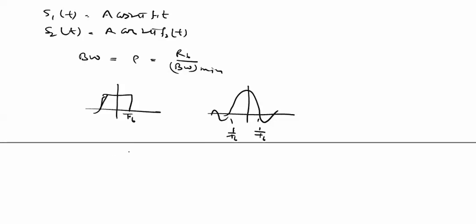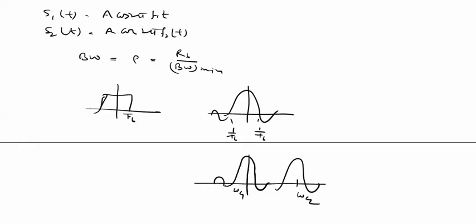If we transmit two different frequencies, means two different components aligned at particular carrier frequencies, omega C1 and omega C2. The difference between these two is omega C2 minus omega C1, plus this component 1 by TB and this component 1 by TB. Both are added for bandwidth purposes, means 2 by TB.